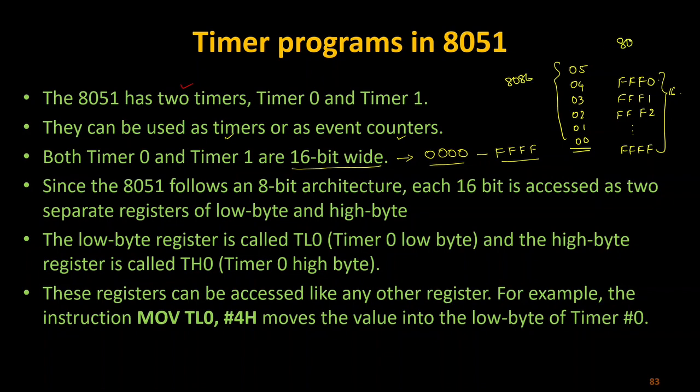Here in terms of 8085, sorry, 8051, it is going to be a little different. The value which we give, after that it keeps on increasing its count, and whenever it reaches FFFF, it stops its timing, or it stops its counting.